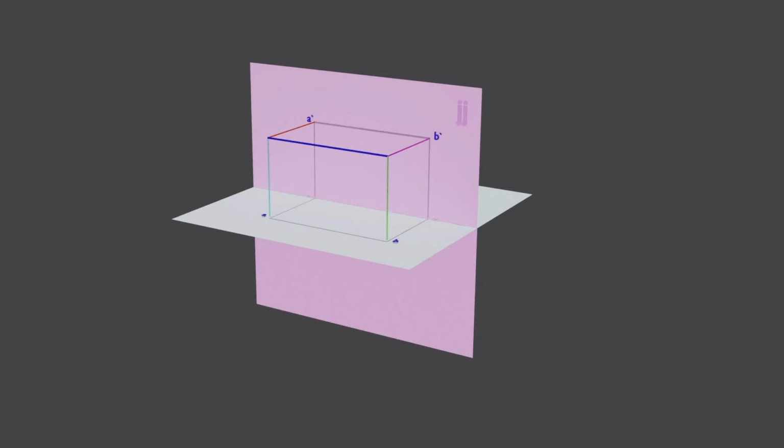So sometimes when you have problems, in those questions it may be given the distance between the end projectors is so much. Okay, so distance between the end projectors means distance between this line and this line. We'll see that when I move on to the front view.